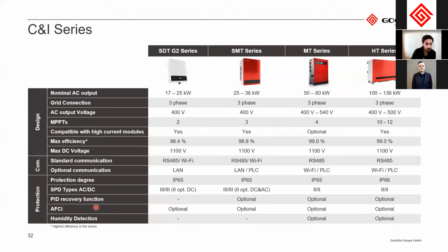AFCI is arc fault circuit interrupter. It's also a safety feature that's optional for all of our CNI inverters, and this basically breaks in case there's a damaged cable on the DC side, it can break or stop the operation to prevent any fire.